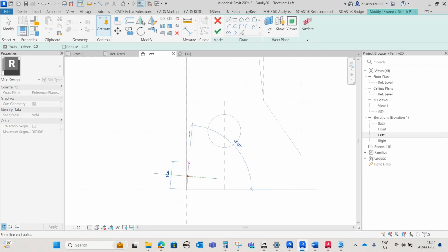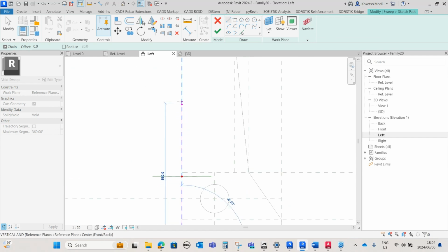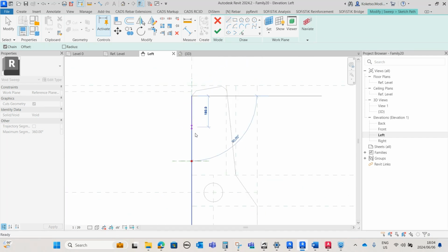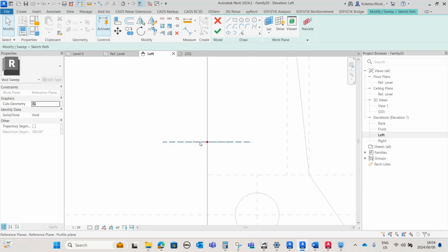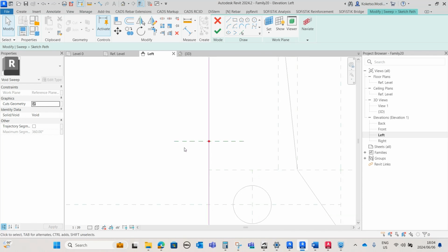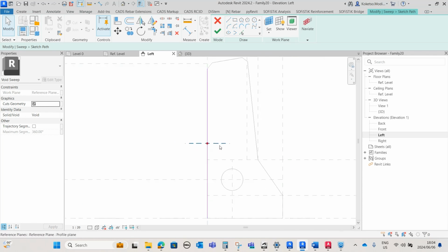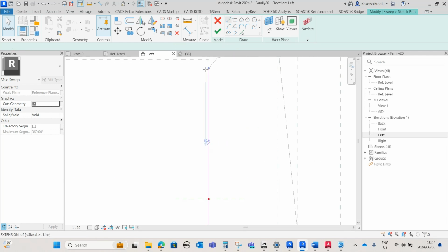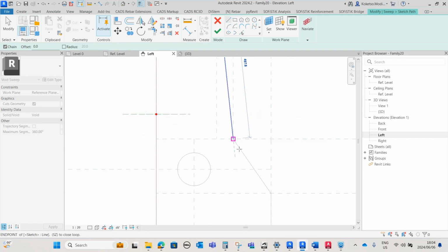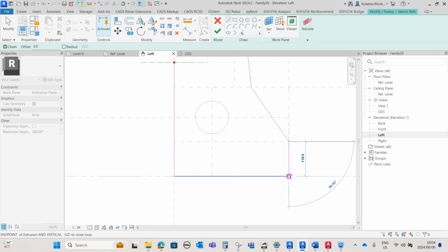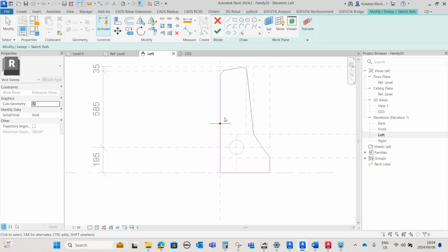And then you're going to draw it from this point. Just make sure, let me just place it like this and press escape. Just make sure this reference line, which indicates how you will apply your profile, is facing downwards, and it's also facing like this on your profile. So you're going to draw your path by tracing over the edges of your barrier like this, and then you're going to place it like that.